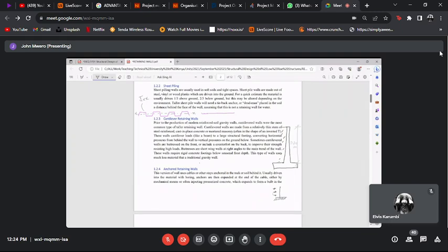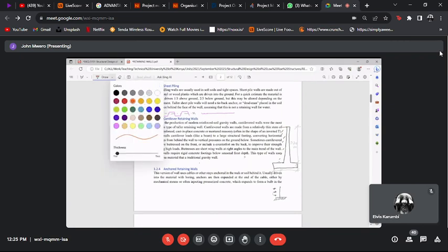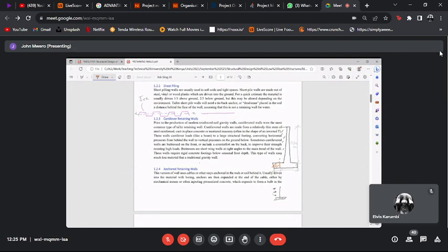So these are very efficient walls, but they require that one does a proper design, and then you size it properly. You do all the checks so that once you specify that this is how I want it built, then it is built that way. The other problem of that wall that had collapsed is that it was not designed. So it was under-provided. Then when it went to site, the site people in their wisdom also reduced the foundation size. So what was in the drawing, which was not adequate, the fellows on site went ahead and also chopped off some of the foundation to save material.